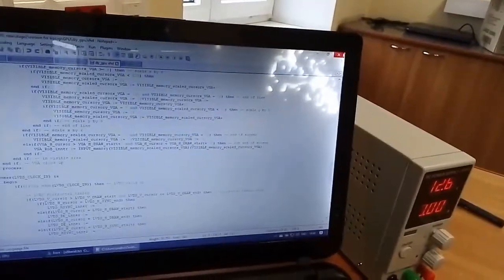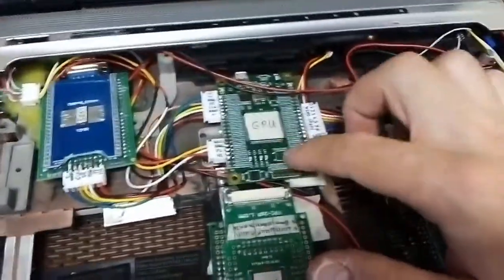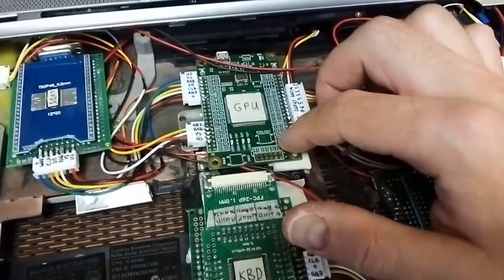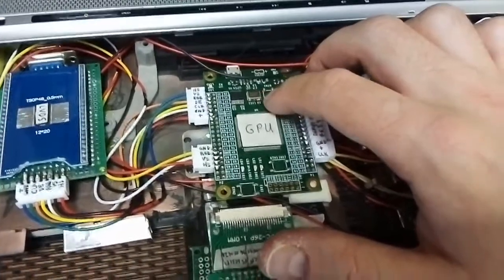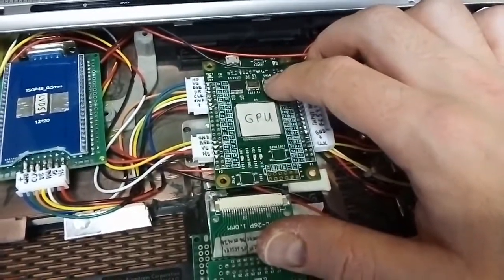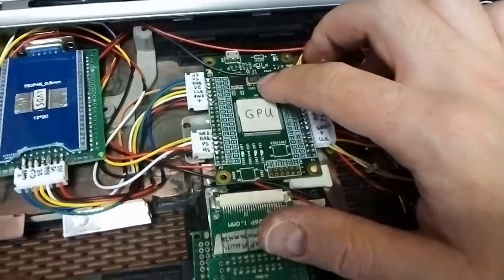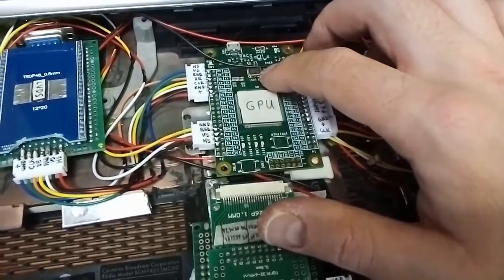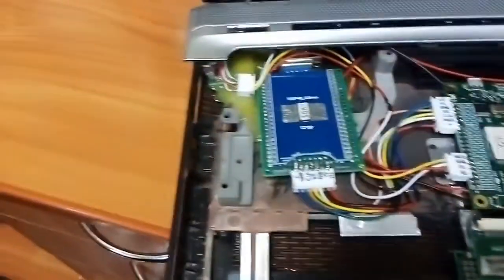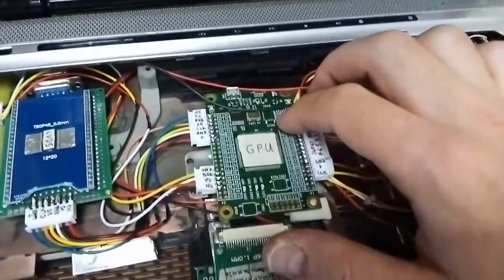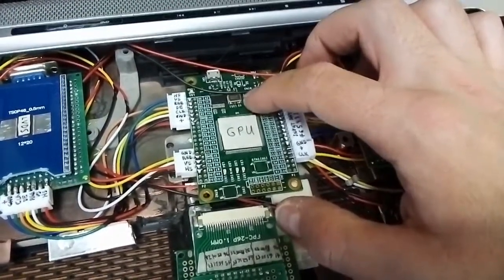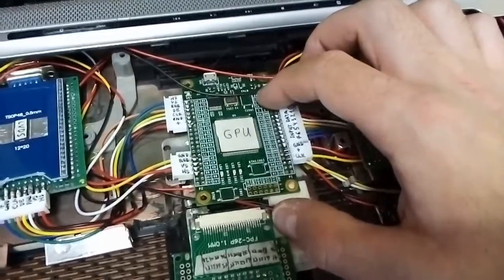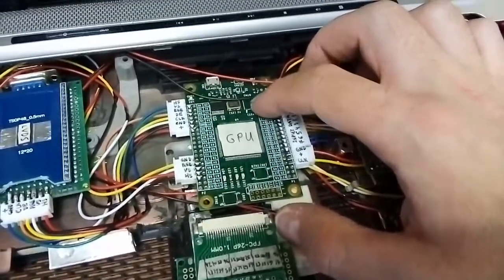And like I said, if you buy this board, then you'll need to replace clocks. Here we have clock 50 megahertz as a rule. We don't need that. We will take that away. We will put instead of it 40 megahertz. That's for the VGA part. And for the LVDS part, it's at the bottom. I have put a 68 megahertz clock. In that case, it's an adjustable clock by resistors, by a few components. Well, all these models I will put here.